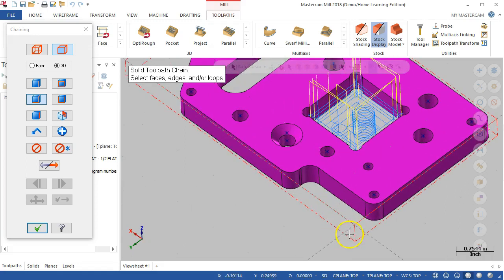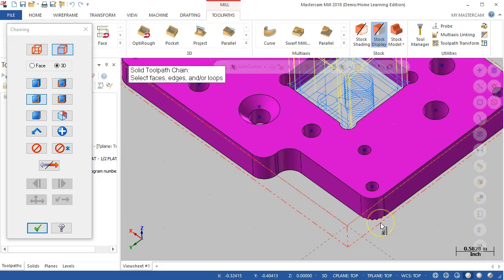And I want to knock this corner off. Now what I didn't do in between those groups was put in that manual entry to do the clamp change. We've done all the interior geometry. We're going to have clamping locations, and then clear of all the clamps. Then on the outside we'll run around the perimeter.